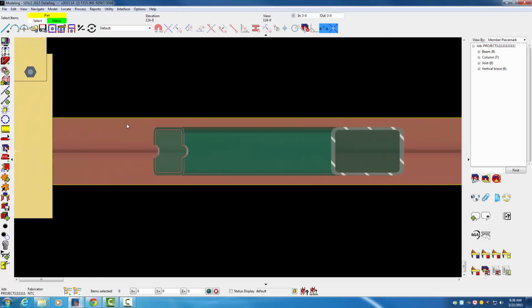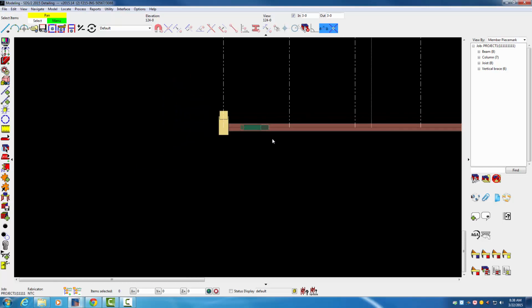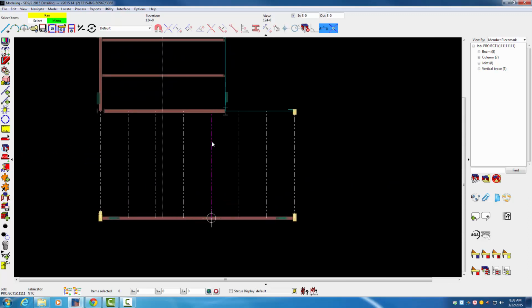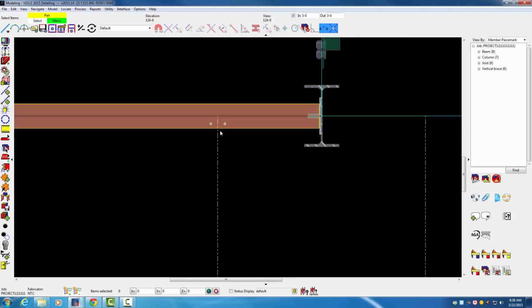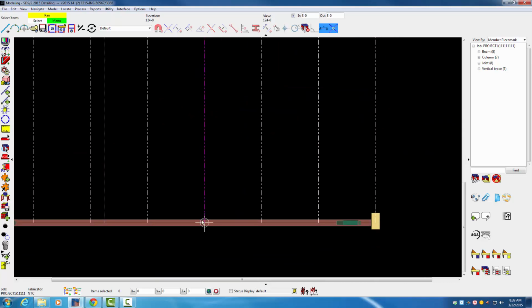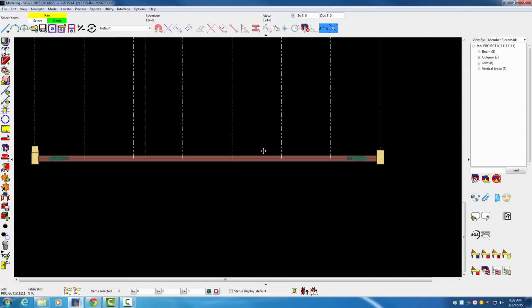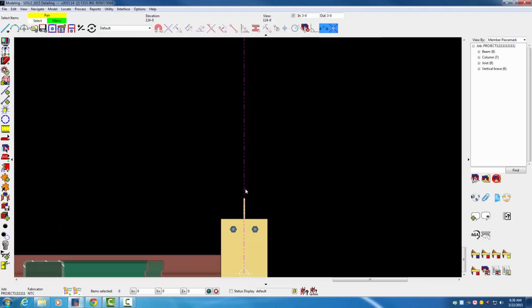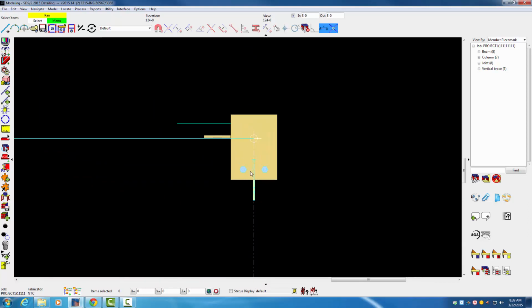This beam here, we'll come back to this one, and that when we get to the bracing, that beam there has failed. If I scroll across here, this bar joist here, if you look on your plans, it shows that it's bolted down. If I zoom in here, you can see it bolted it down. There's 2 bolt holes. If I go to the other end, zoom in, you can see 2 bolt holes. So that connection is working. Check the other joist over here. Got 2 bolt holes. And again, 2 bolt holes.